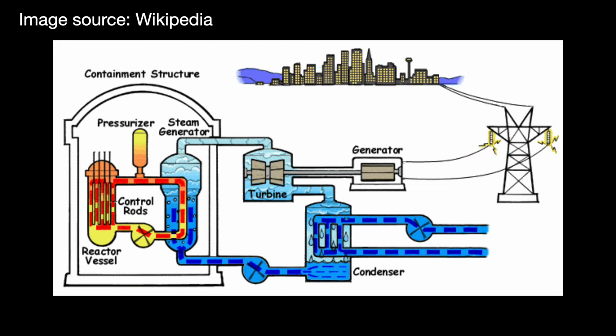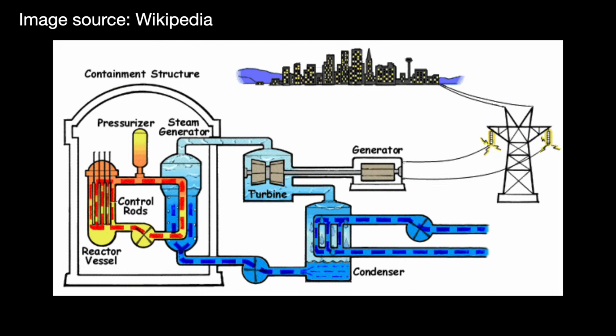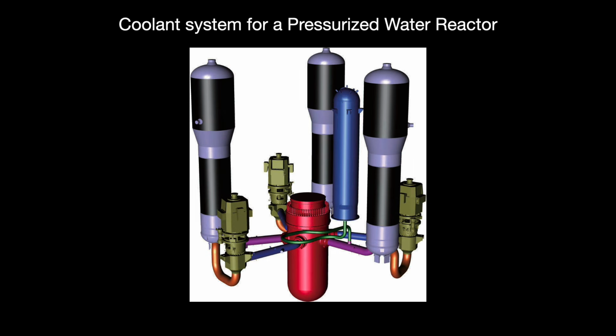seawater brine being desalinated. There should be at least 2 loops and barriers between them, usually the steam generator and a heat exchanger. The key issue would be to prevent leaks in any of the loops from contaminating the brine with radioactive material. For instance, a leak in the steam generator might release gaseous tritium that then permeates into the water later down the cycle.